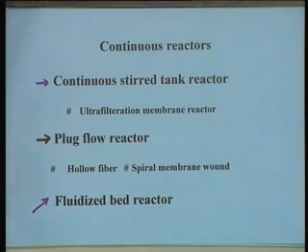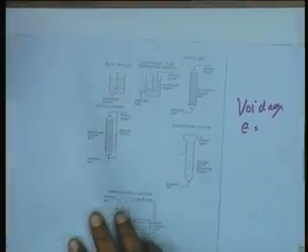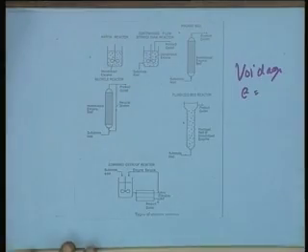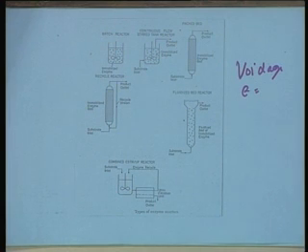is in the form of your CSTR coupled with an ultrafiltration cell. Now, particularly in case where you want to carry out reactions using insoluble substrates or soluble enzymes in a CSTR and want to use a continuous reactor. Now, obviously for a soluble enzyme you cannot use a plug flow reactor. So, a CSTR coupled with the ultrafiltration reactor can be easily used for carrying out reactions with the soluble enzyme or with insoluble substrate. Why can't we use a plug flow reactor?